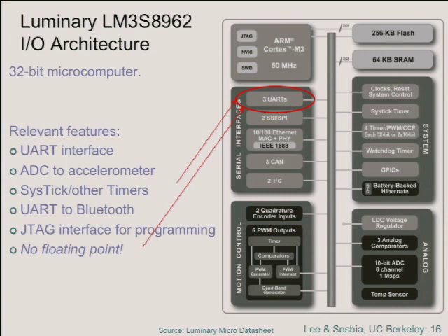The third one turns out to be the killer one. It used to be that you were willing to pay the price of more expensive connectors and wires because the performance was better on parallel connections. The serial connections have gotten much better, and they actually outperform the parallel connections these days because of the synchronization problem.